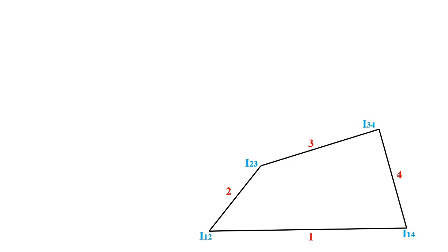We can also say that if we combine bodies 1, 3 and 4, the instantaneous centers are I13, I14 and I34. Therefore, I14 and I34 we have here, and the line joining I14 and I34 is already a link. So you join I12 and I23.